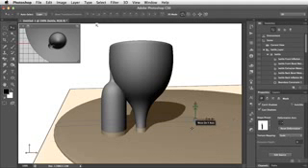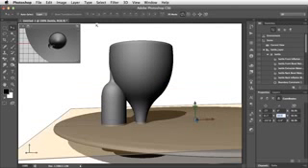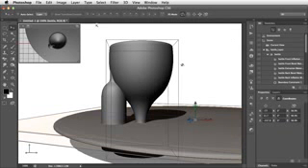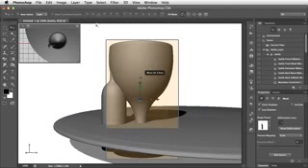If we go onto the Properties panel, we can now look at the Mesh tab, and we can set the coordinates. So let's set the rotation angles to 0. So now we know our table is sitting flat on the ground. Let's take the glass next.